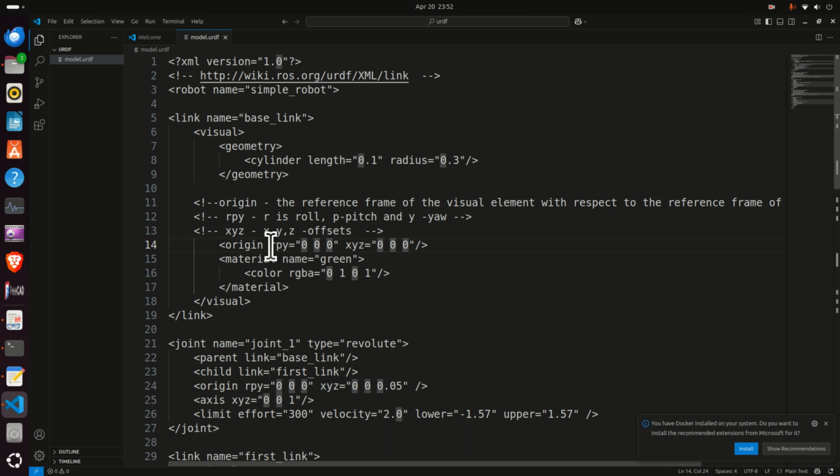And these angles RPY represent roll, pitch, and yaw Euler angles, which tells you how the coordinate system axes are being rotated with respect to the base or the world coordinate system. Here I need to be precise and say Euler angles that define rotation of the frames of this coordinate system with respect to the axis of the coordinate system associated with the world or some fixed coordinate system.